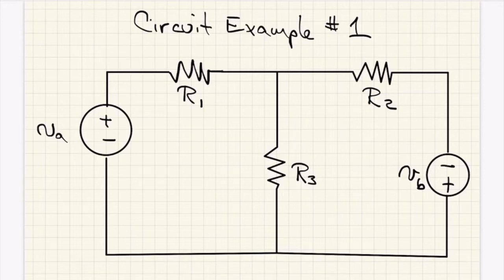And so the first thing, once we've got the diagram figured out, is to label the currents and then the resulting voltage polarities. Really, we don't know the voltages yet, but we know which is going to be plus and which is going to be minus. It's traditional to take the resistance R1 and say the current that is going to flow through that, I'm going to call I1.